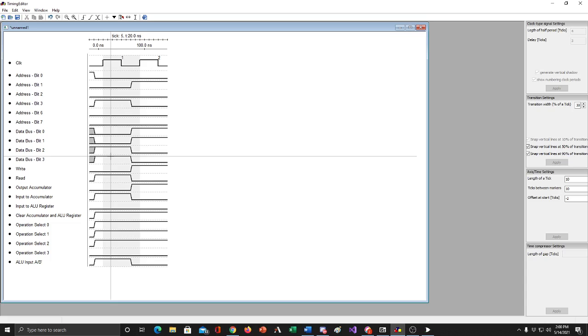So those were the things that we needed to do, that in 2 clock cycles we retrieved the read-only memory value in position 3, which put something onto the data bus. So we read that information. We had to store the result into the accumulator after selecting the not operation for the ALU.